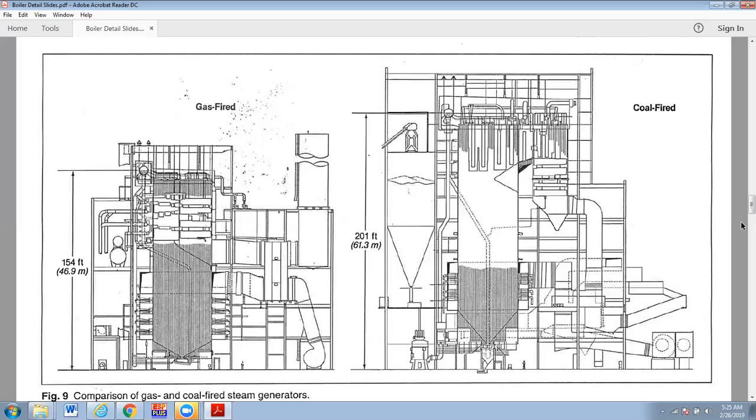I think because of the increased efficiency, if you want to burn the natural gas, you would just build a combined cycle plant, because this converted coal boiler would still not have a great efficiency. I mean, you might get 35, 36, 37%, but I'm pretty sure you would not get to 40. And that combined cycle plant can be in the mid 50s up to maybe even 60% efficient. So if you're going to spend a significant sum of money, why not spend a little bit more, or maybe a lot more, but get a much more efficient unit? So I think that's what's pretty well been done in the past.